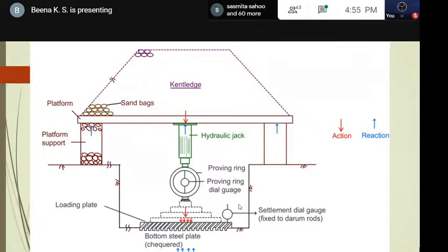So in gravity loading, the jack can be looked upon as progressively transferring the dead load on the platform to the soil, the maximum value of which is the full dead weight. Since the platform will get lifted from its support at that stage, with the jack alone carrying the entire load, it is necessary to load the platform with a load higher than the estimated bearing capacity by a comfortable margin. In the same way, the truss must be designed for the same higher load acting upward and the reactions acting downward.